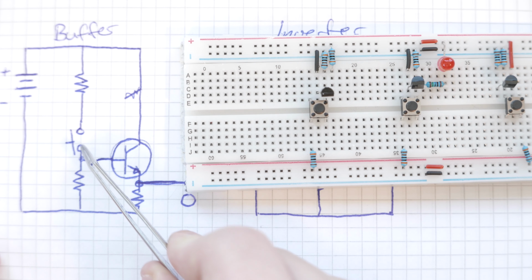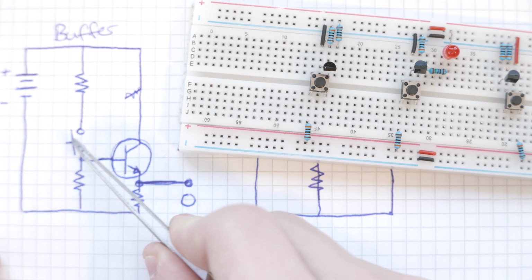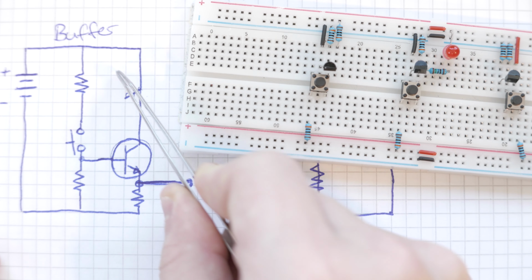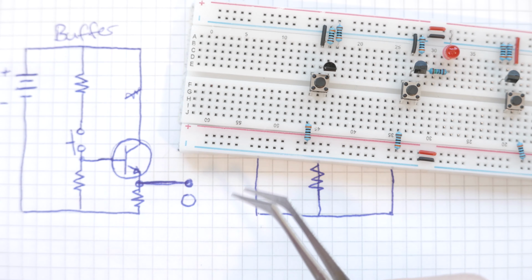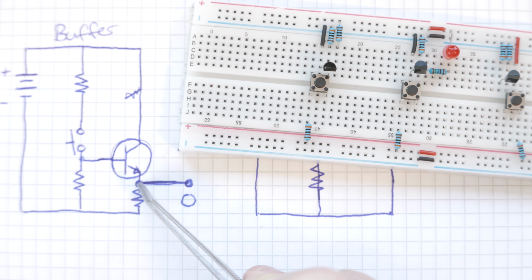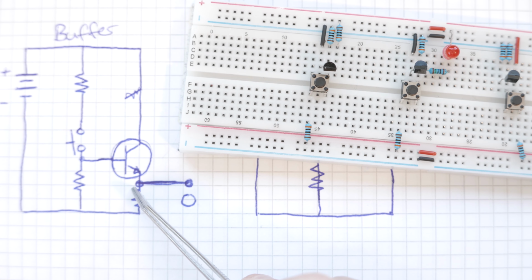So you'll see that when I flick this switch, it will allow the current to flow from 5 volts through the transistor, and you'll see that this time the resistor is on this side, and we take the output signal here. And the reason for this is that the output is, of course, with respect to ground. And with respect to ground, at this node, right now, after the transistor, it's 5 volts. And because it's 5 volts, we can use that.